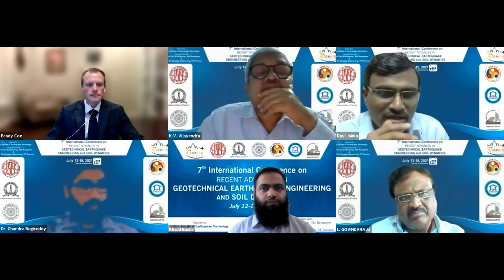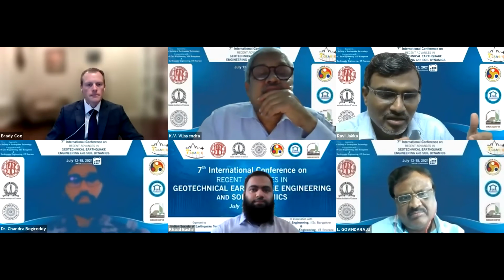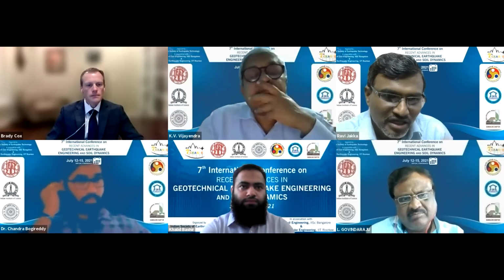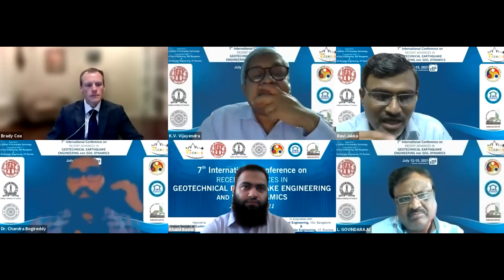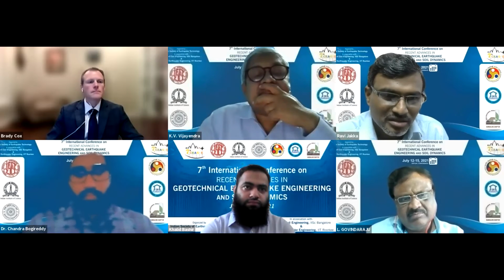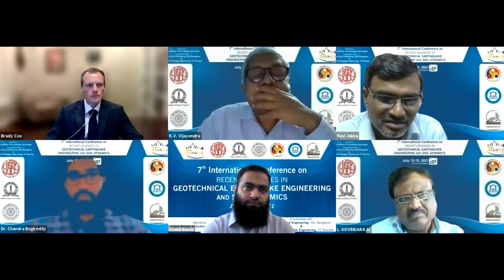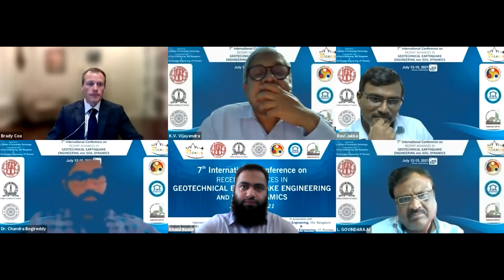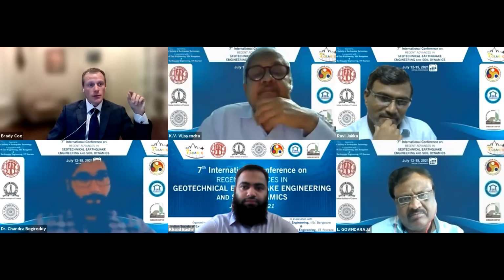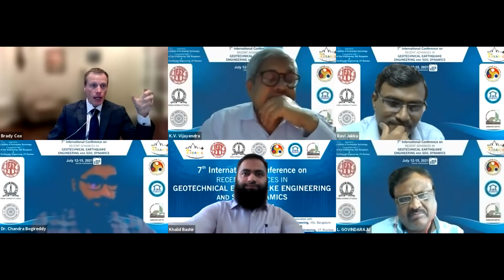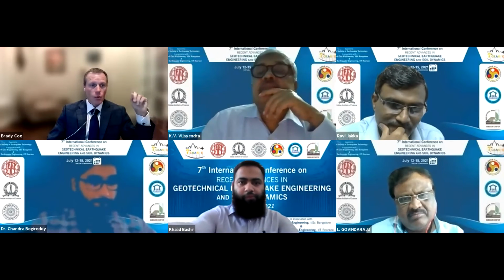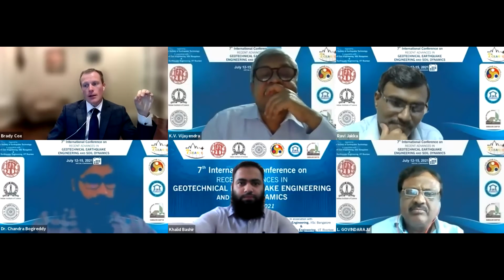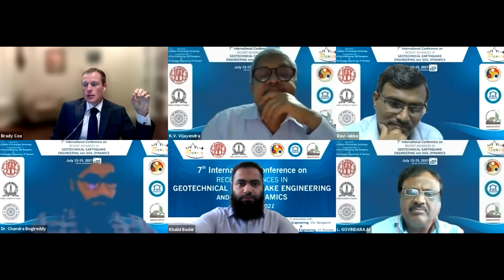So in coming up with that pseudo velocity profile, can't we use the amplification of H/V along with maybe the damping based on the thickness? So yeah, there's one school of thought that says that we could invert the H over V data at every sensor location and develop a 1D velocity profile beneath each receiver, and that might provide some useful information.